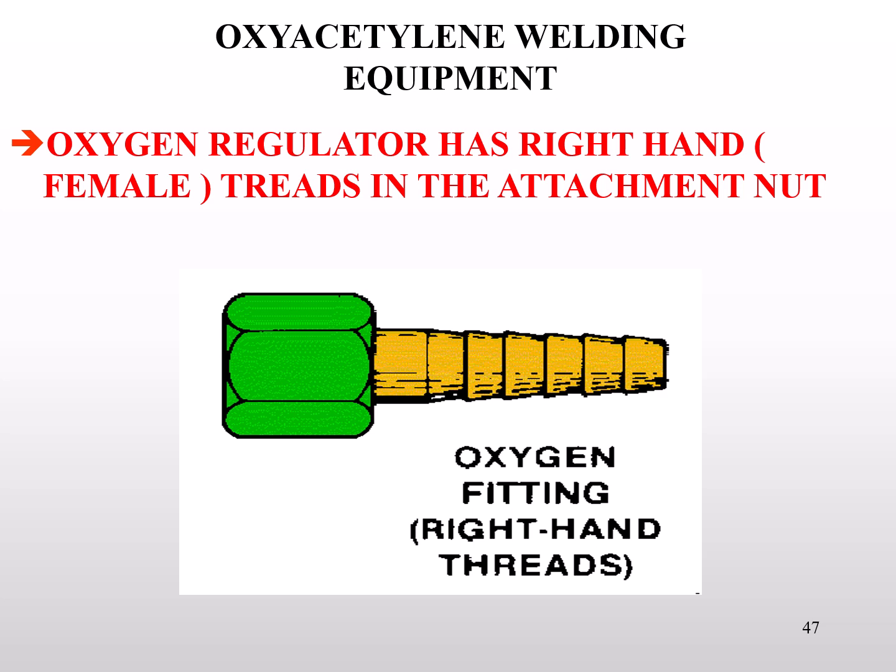Oxygen equipment has right-hand or common threads. It's the same threads we would use in hardware. Left-hand threads are kind of uncommon. So all of your oxygen equipment, to put it simply, is righty-tighty, lefty-loosey.